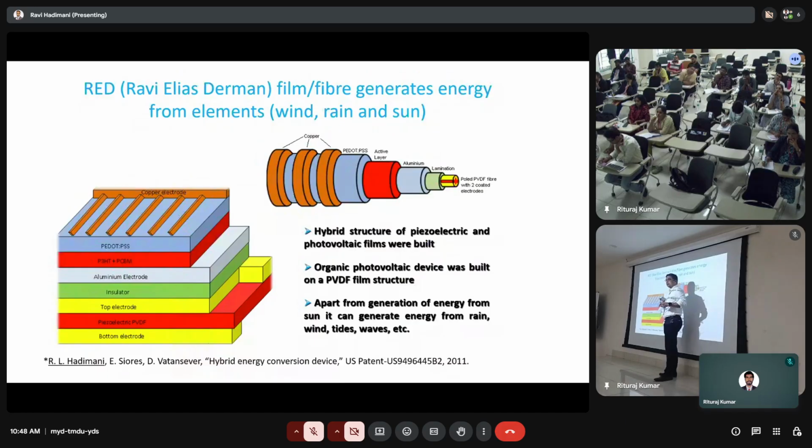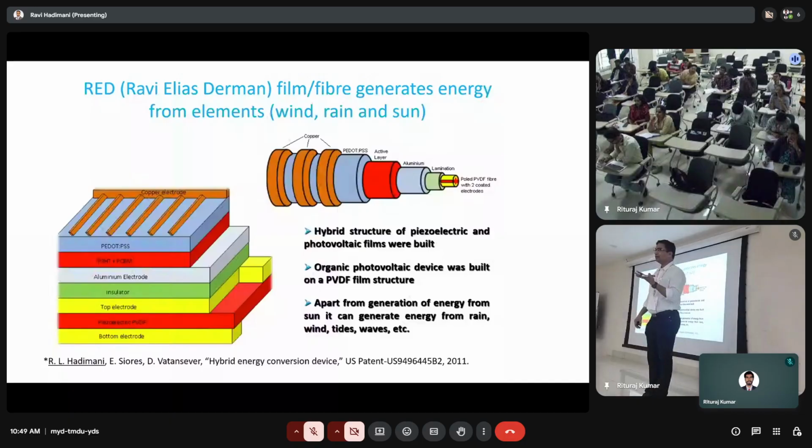It was a lot of work. First, getting to know what these compounds are. Those were very expensive compounds. And depositing electrodes on PVDF is not easy because when you deposit any metal electrode on a polymer, you damage the polymer, right? So you have to identify a technique that deposits at room temperature, at lower temperatures.